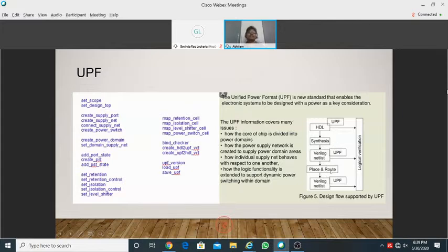So your functionality, just like RTL, is being taken into consideration. So you don't need to worry that the information described at one level is being lost in another level. So this UPF is carried forward at multiple places within the SOC. So that is where you will have the power intent being properly put into the design and also verified at each level of verification.